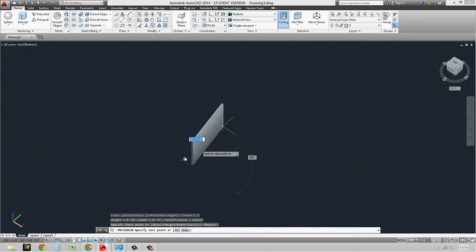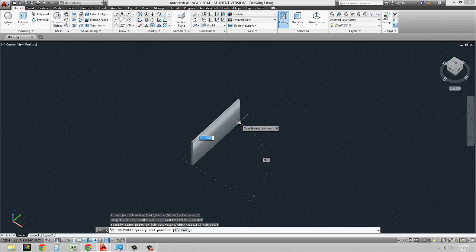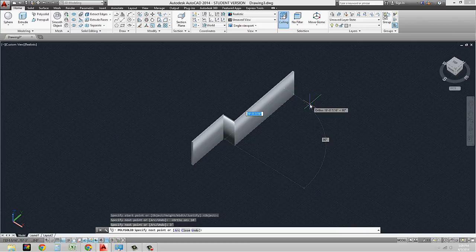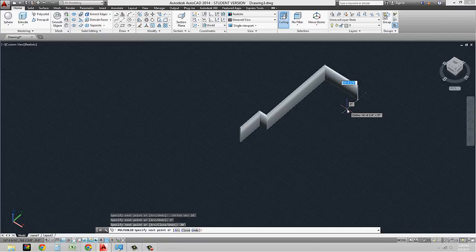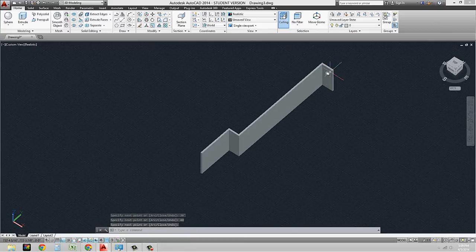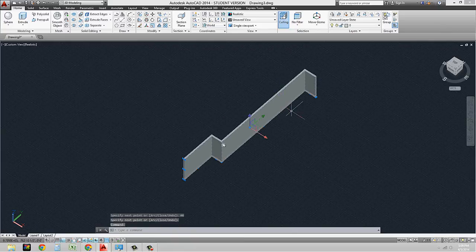my start point. And basically what I can do is, for this example, unless you want angled walls, I'm going to turn on my ortho, so I can say, well, I have a wall going this direction 10 feet. I'm going to say 3 feet in this direction, let's say 30 feet in that direction, 40 feet in that direction, not 40 inches, I guess it took 40 inches, and then you could hit enter, and it basically laid these walls down as one singular object, but you could actually work with it like you do the line tool or the polyline tool.